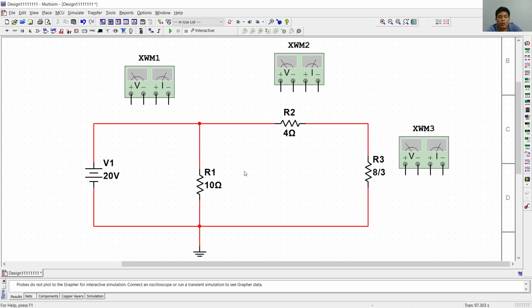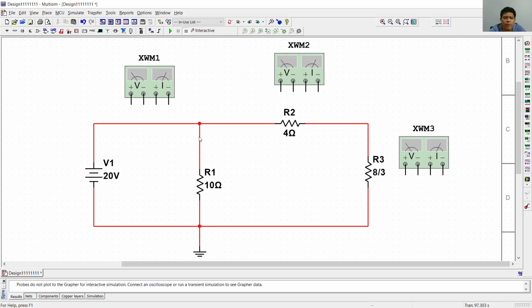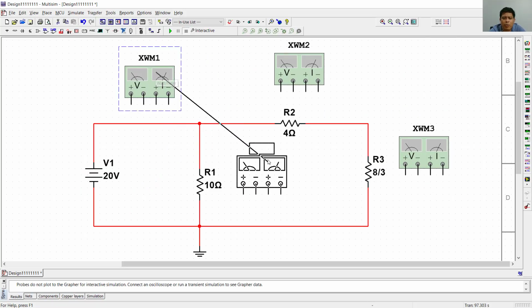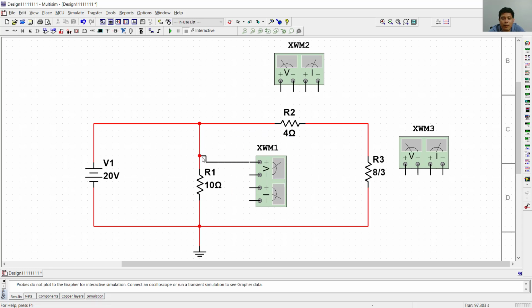So, in which element do we want to connect? We want to connect in this element first. So let me connect the wattmeter in this element first. Voltage, let me rotate this so I can connect voltage here, positive, negative, ready, set. But now, how can I connect current?